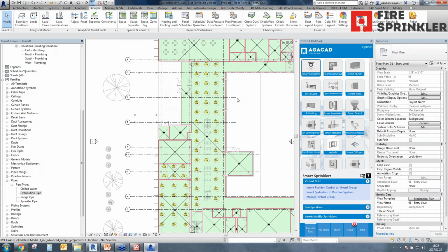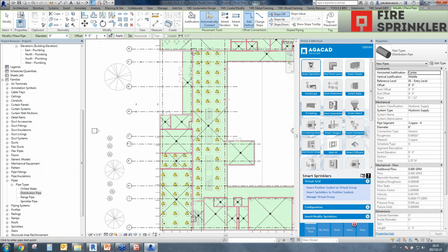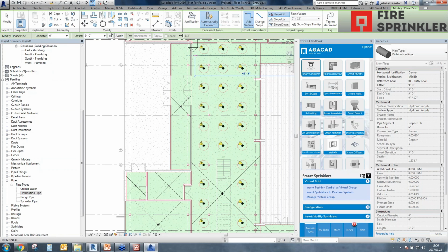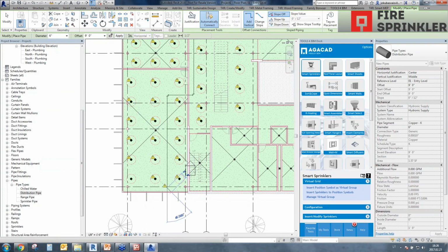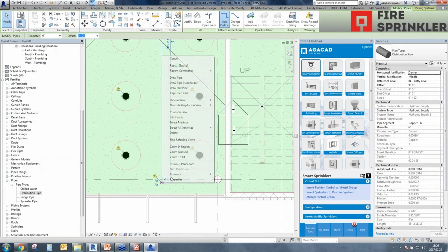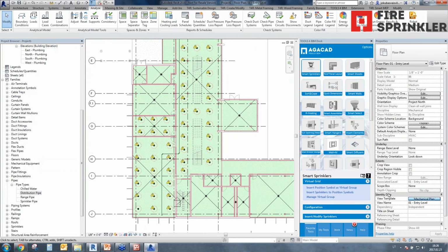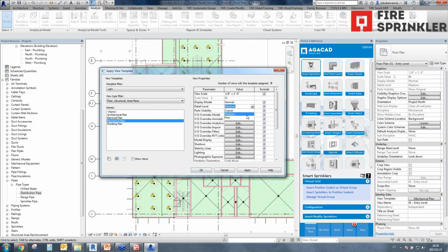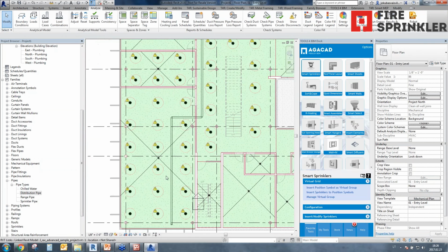Okay, let's go back. So I'm just taking my ductwork, I'm placing it at 9 foot. My pipe diameter is 6 inches, and my pipe will go like this. It will go down to some place, and it will go left and down again. Okay, I will place a cap here as the example. Okay, let's make a better visual representation. Define, and as you can see, we have distributed our pipeline.